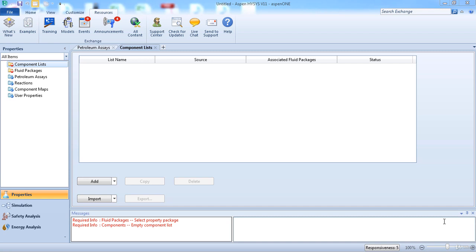It consists of a column where absorption takes place between triethylene glycol and water. Then the rich stream goes to the regeneration system in another column by reversing the operating conditions to be low pressure and high temperature. First, let's add a stream.